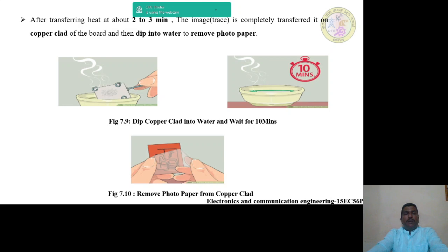Next, after transferring heat about 2 to 3 minutes, or the image is completely transferred on the copper clad of the board, then dip this copper clad into the water to remove the photo paper. Wait for 10 minutes and then remove the photo paper slowly.